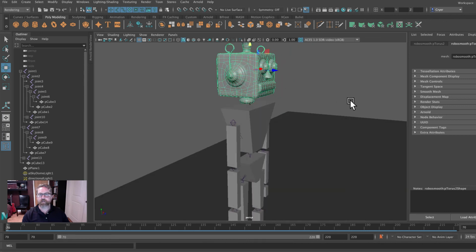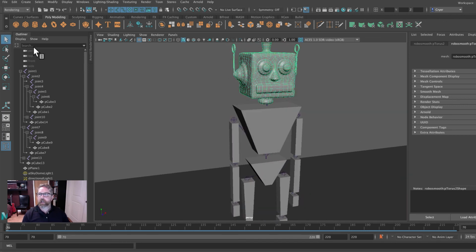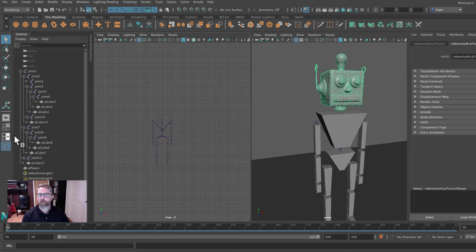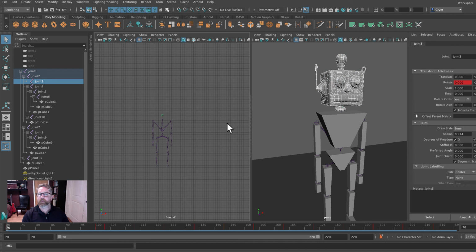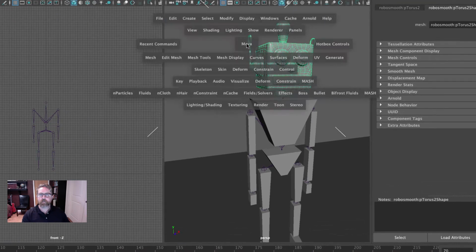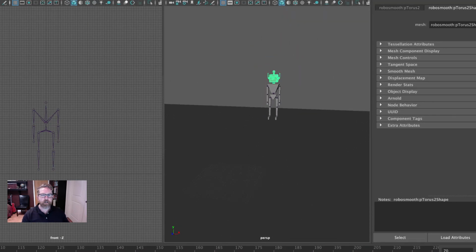And all we have to do is now parent this in. So we've selected the geometry. And we'll come and select the joint. If you wanted to go back to do the same two side by side, you could. So I've got this selected. I'll shift select the neck. Right, our child was selected, our new head. Shift selected joint 3. And lowercase p will come to edit parent. And as you'll see, that just allowed us to swap that out entirely. And we can press play.